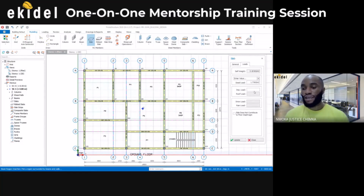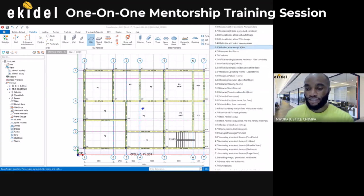Okay. Now here that says imposed load, which is the live load, just right click there, you will see several loads based on the type of building you are designing for or the usage. So in this case, we are designing for what? Residential purposes. So I'll come here and select residential building, this one here, this is 1.92. If you're doing for office building, you can see offices here, you can see for hospital, school classroom, the different categories here. So I'll come now and pick okay.